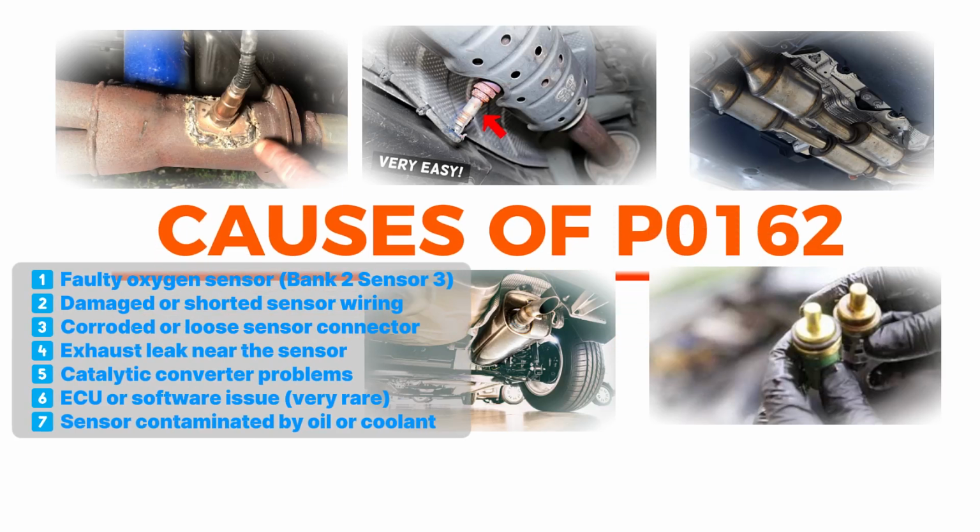Here are the most common causes. 1. Faulty oxygen sensor. 2. Damaged or shorted sensor wiring. 3. Corroded or loose sensor connector. 4. Exhaust leak near the sensor. 5. Catalytic converter problems. 6. ECU or software issue. 7. Sensor contaminated by oil or coolant, and heat from the exhaust often damages wiring over time.